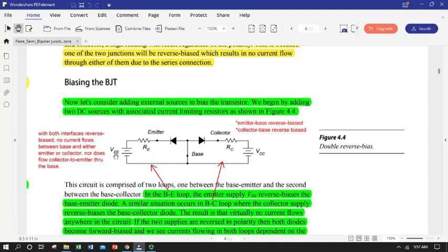And that's what that subscript double E means. And so we're gonna put the positive end. We're always going to put a current limiting resistor, even though this is just a model. We're getting in the habit of always putting in current limiting resistors. These are heat sensitive devices. We don't want a bunch of current screaming through them. So we're getting used to good practice here, even in our schematics.